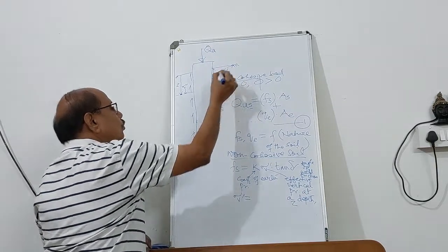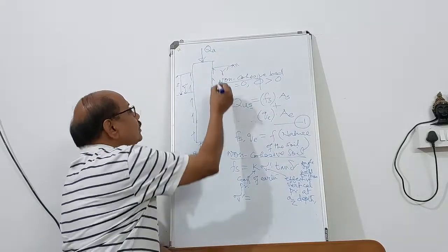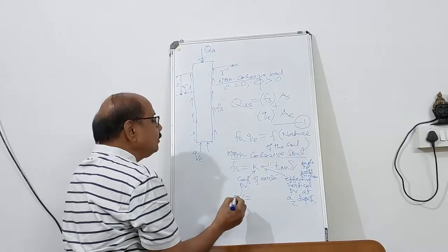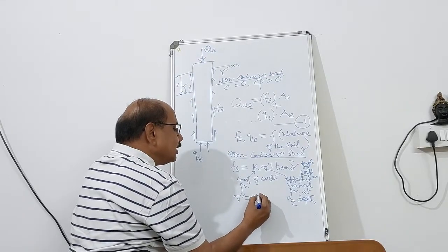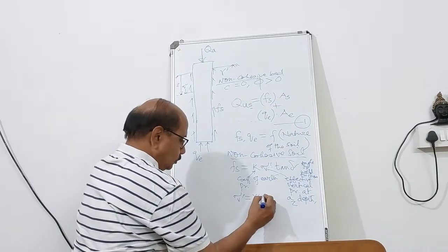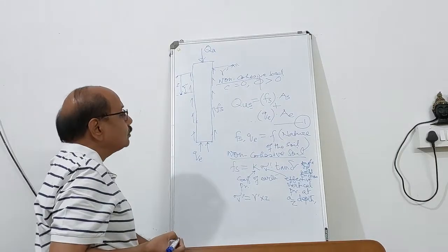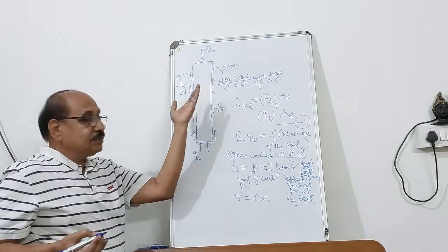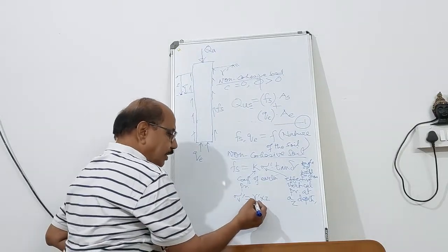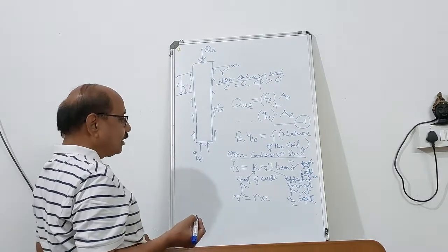You should know the ground properties. Here the effective unit weight is gamma prime. This effective unit weight multiplied by the depth will give you the effective vertical pressure. And gamma prime is the soil property which you can find out. So effective unit weight multiplied by Z is equal to the effective vertical pressure.